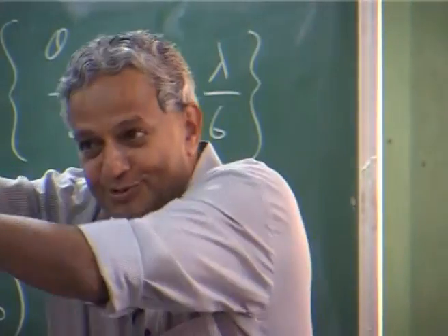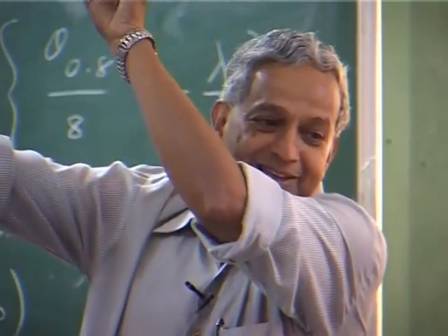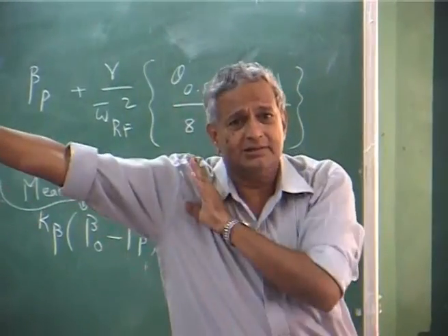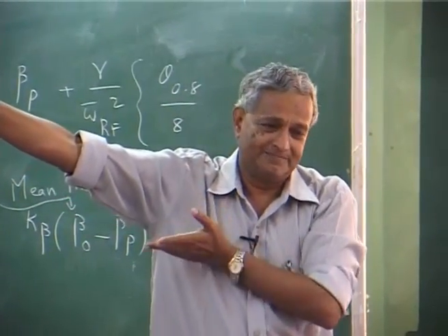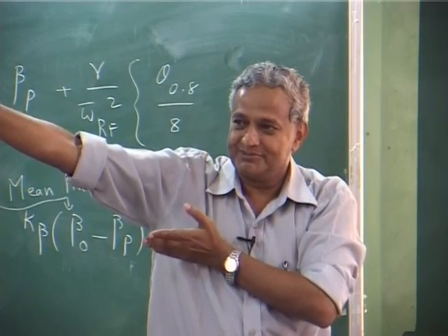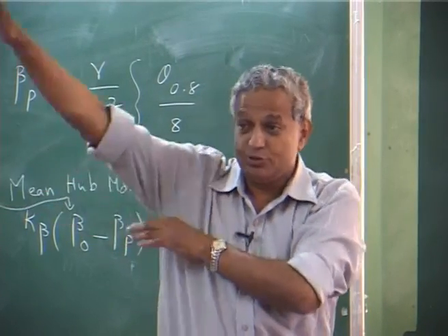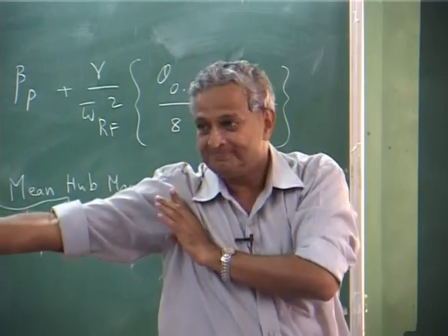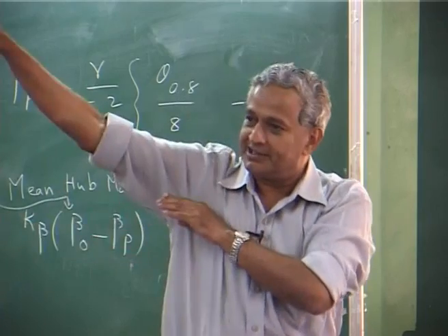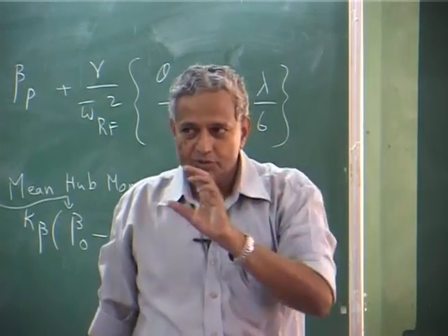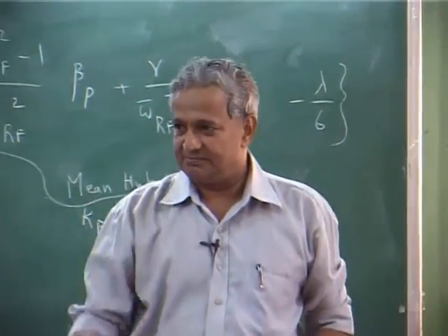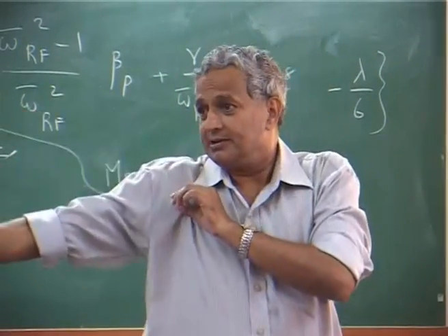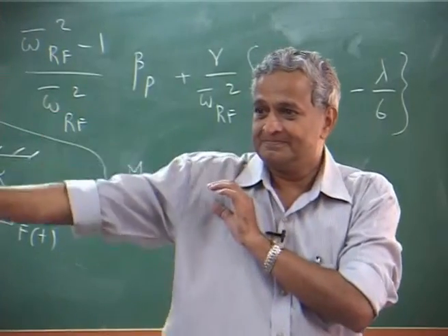So, because the centrifugal force will try to bring it down, the aerodynamic force will try to take it up. If these two moments are equal, it is kept at the same location, that is all. Okay. But if it is fully up, it will try to bring it down. If it is like this, it will take it up. So, that is why usually you do not look at flap deformation, because depending on the flight condition, it can come down, it can go up, anything.